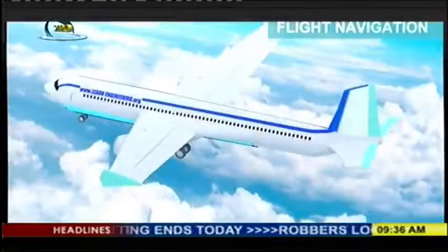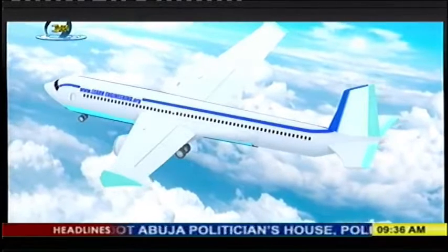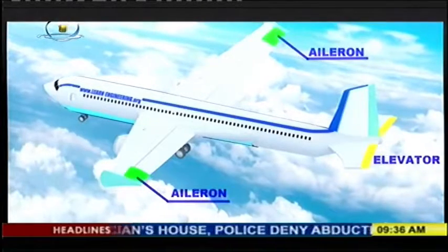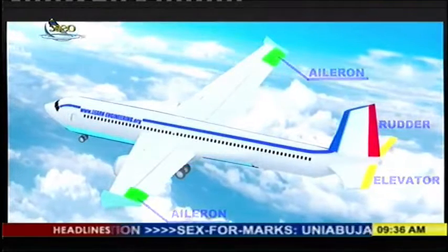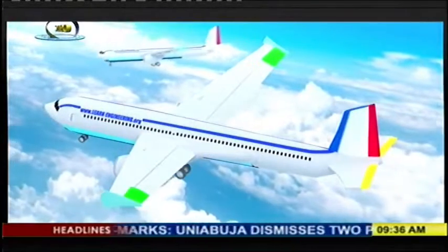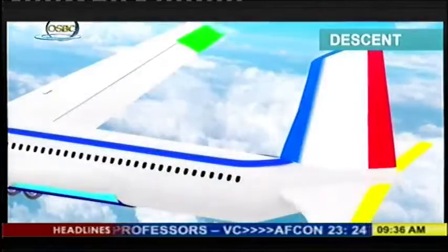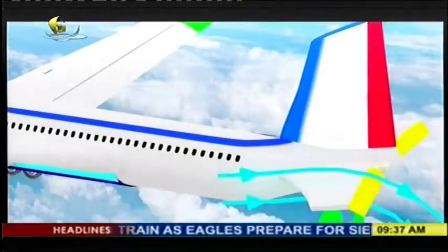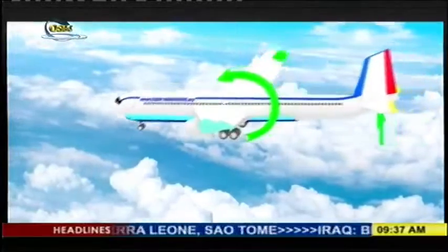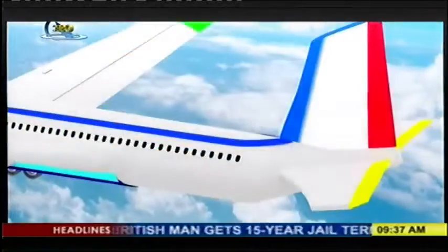You can navigate the airplane the way you want with the help of three different wing attachments: aileron, elevator, and rudder. Pilots use them alone or together depending on the situation. Assuming you want to descend the plane, you can just lower the elevator. This will deflect the airflow as shown and will produce a lift. The lift force will create a moment that will make the nose of the plane go down. If you want to climb up, do the reverse.